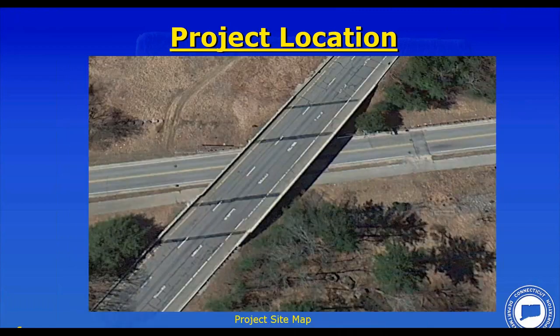Zooming in a little closer on the bridge, the traffic volumes are fairly low on 395 in this area. However, you might say, wow, look, Mike, there are 3 lanes of traffic on this bridge. It must be a high ADT bridge. The reality is we're fairly close to the acceleration lane from the on-ramp for the interchange just to the south of the bridge. So this particular bridge has a climbing lane or an acceleration lane that goes across. The third lane is not necessarily there for ADT. It's really there for the acceleration of vehicles coming up the highway.